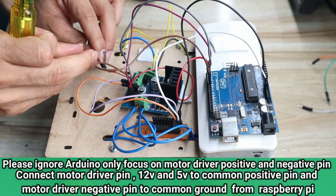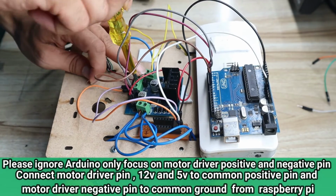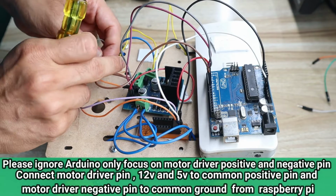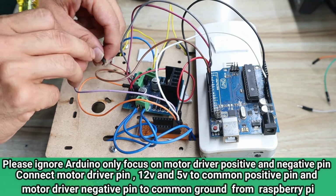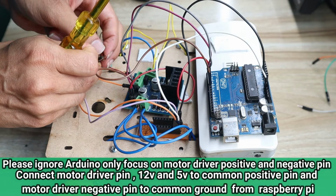And this ground pin should be connected again to the middle pin. So on the middle pin, there is already ground from the Arduino. Just plug it out there and take the common ground. So there should be 2 ground pins, one from the power supply and one from the Arduino.